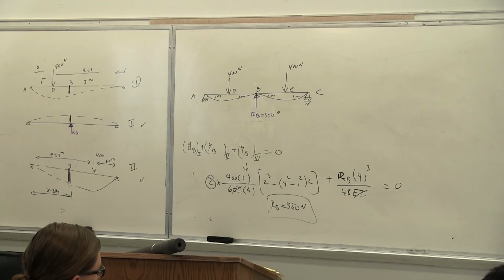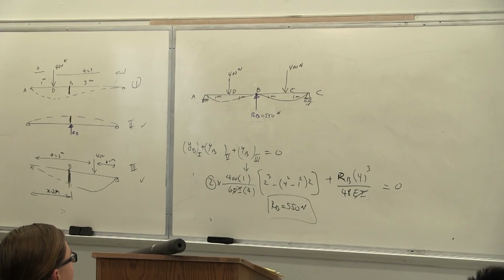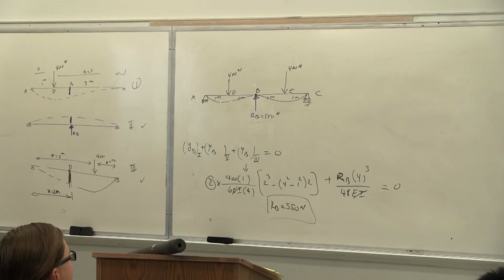We always check the deformation, but deformation is for some machine part, something you want to have very small deformation, and we always are careful about that. But deformation is not the issue generally. First, the design is the issue. Is that correct or not? But after you design it, you don't want deformation to go beyond a certain limit as well, because after all, your equation is not going to be valid anyway if you have large deformation. Is that correct or not?